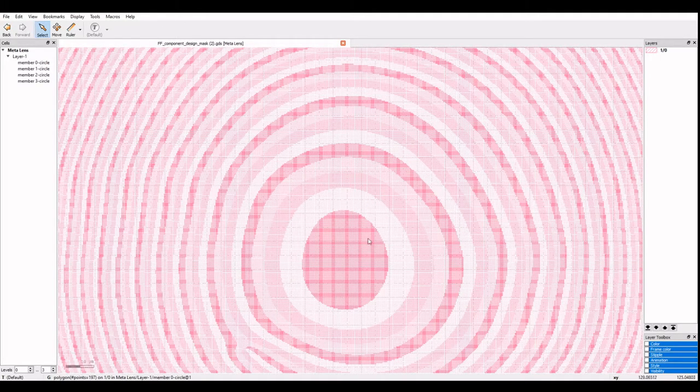You see there an irregular shape that's caused actually by the iterative algorithm that does not always produce a perfectly symmetrical wavefront, but instead tries to approximate the far field as best as possible. This can sometimes lead to things like optical vortices and also an irregular pattern in the GDS mask. Like this, we have a GDS file of a MetaComponent that will approximate the far field that we put in as a target. And that's how you make a far field target design using the PlanOpSim software.